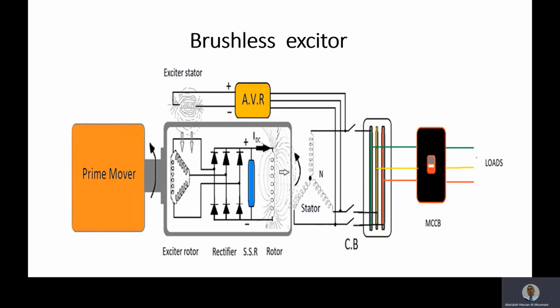Again, we will concentrate on the frequency fault. If you have a reduced frequency in the generator, it means you have a mechanical problem in the prime mover. Check the fuel racks or the filters. Maybe you will find one fuel rack is stuck or something, and maybe one filter is blocked. So this is for the reduced frequency of the generator. It is not an electrical fault, it is a mechanical fault related to the prime mover.